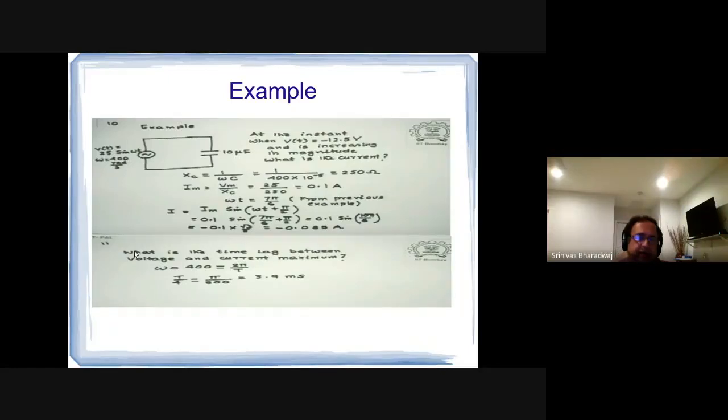So d phi by dt, negative d phi by dt, equals EMF, right? And therefore, what happens there? V equals L di by dt. That is a more traditional way. And in an electrical circuit, if L di by dt, this one is sine omega t, that one will be cos omega t. Okay, so that one will be lagging.